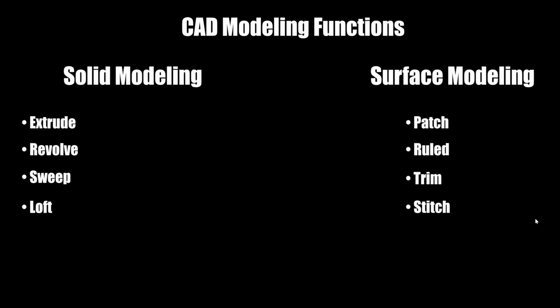Stitch command can be called differently in other brands of the CAD software, but stitch command will convert watertight surface into solid, because at the end you have to convert surface into solid, either for CNC machining, 3D printing, or making a 2D shop drawing. You need to convert surface into solids to be able to do that.